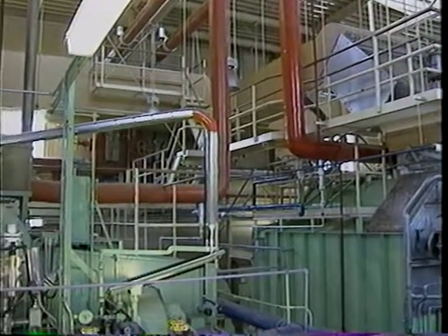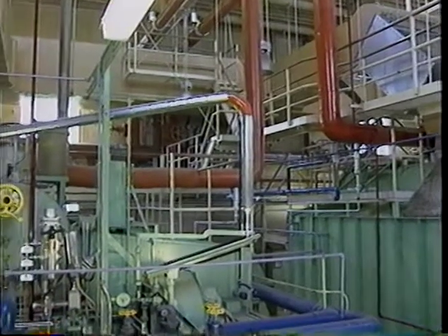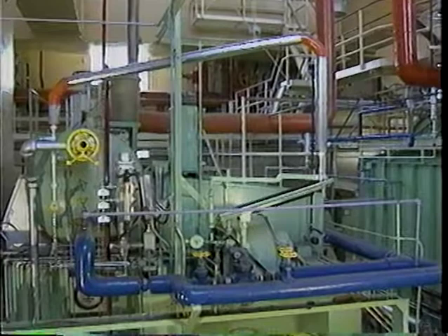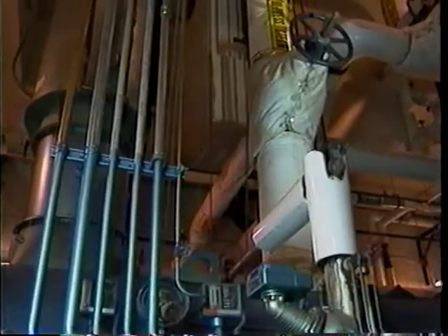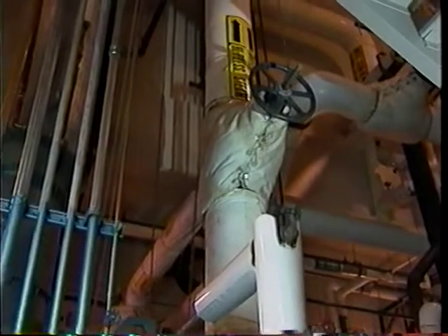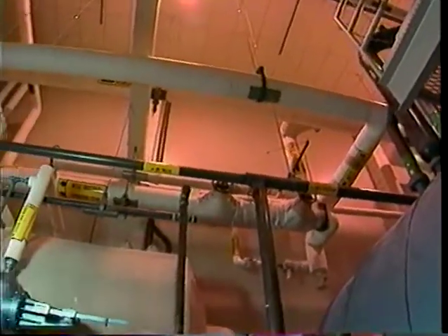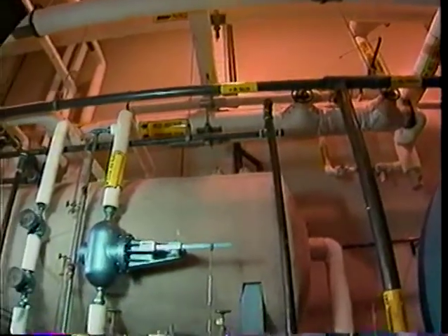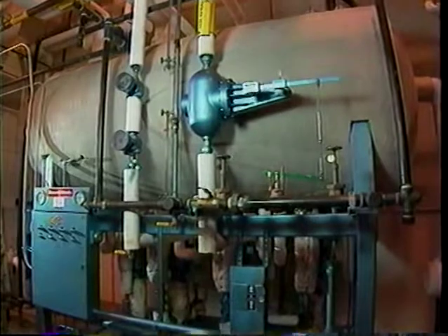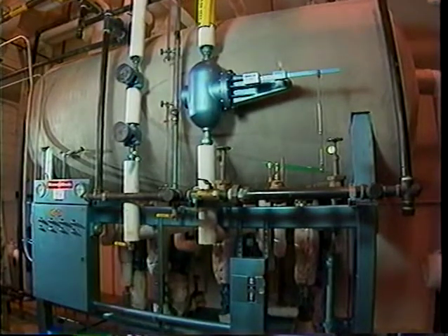Water and steam fittings and accessories are required to supply and control water and steam in the boiler. Boiler fittings, or trim, are components such as valves directly attached to the boiler. Accessories are pieces of equipment not necessarily attached to the boiler, but required for the operation of the boiler. All boiler fittings and accessories must be constructed in accordance with the ASME code.